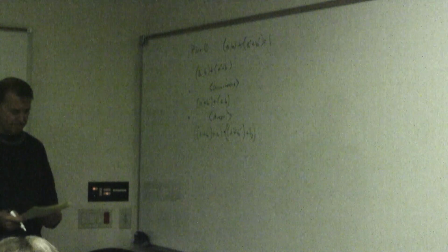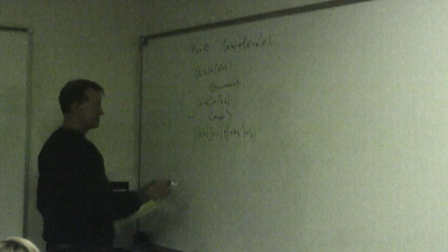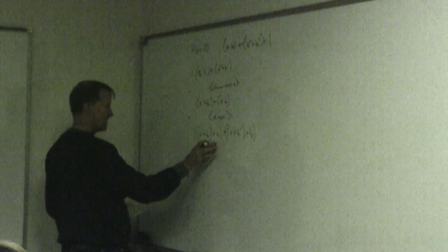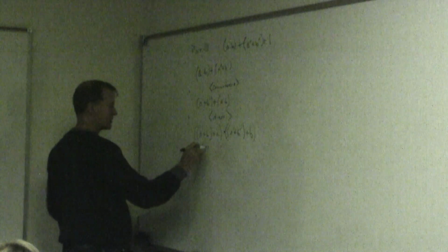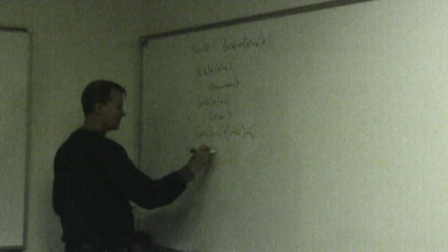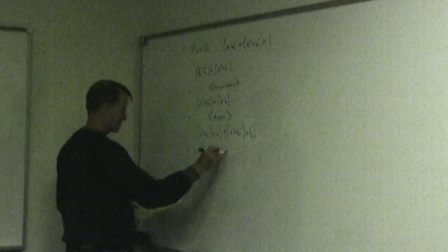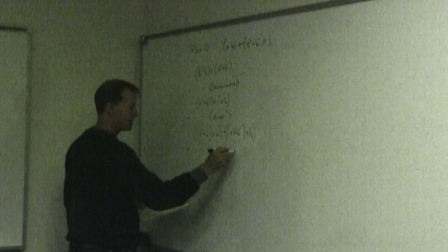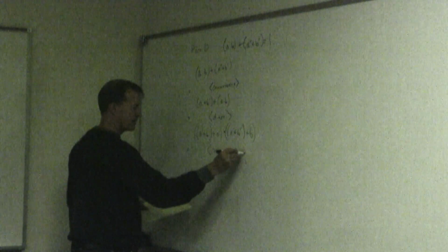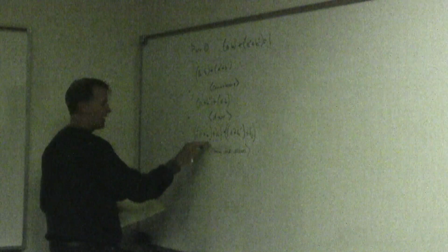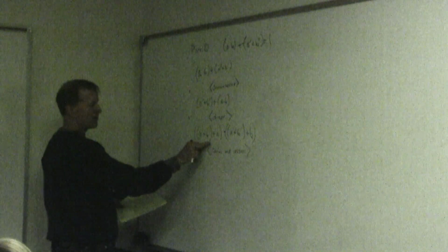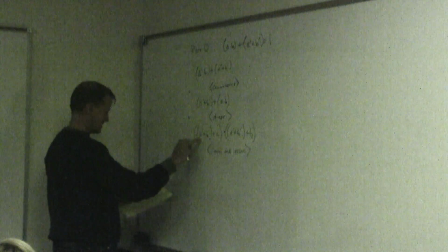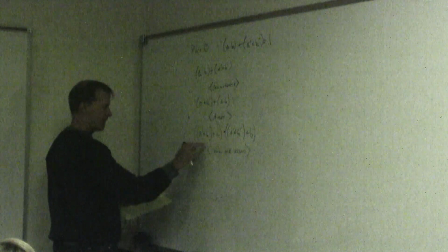And since those are all the same precedence, we can get rid of the middle parentheses. We can use commutative and associative. By the associative law, this parenthesis doesn't matter, and we can move this A next to this A prime. We want to do that on the B side as well.